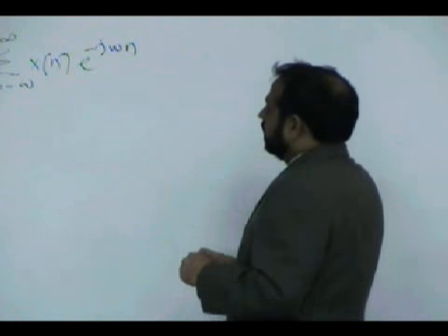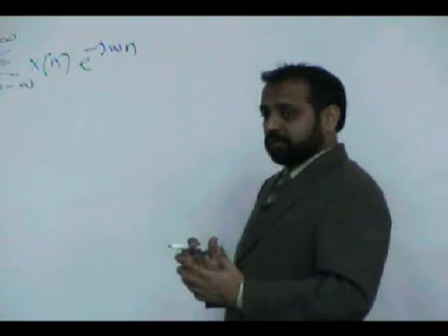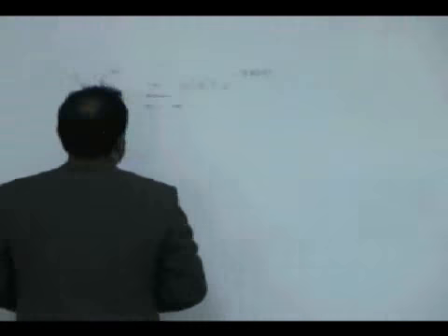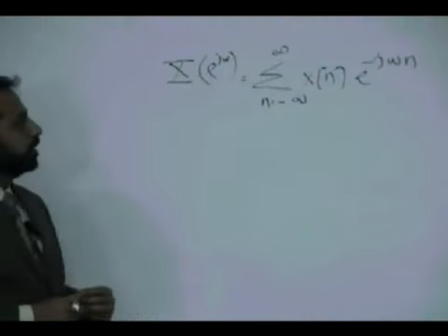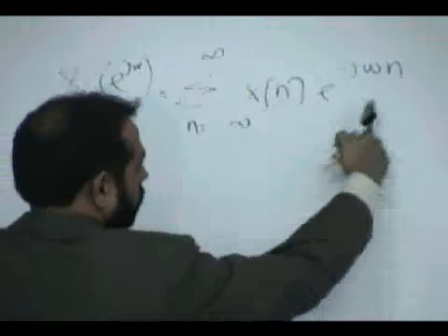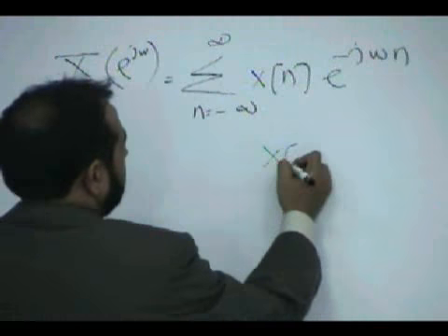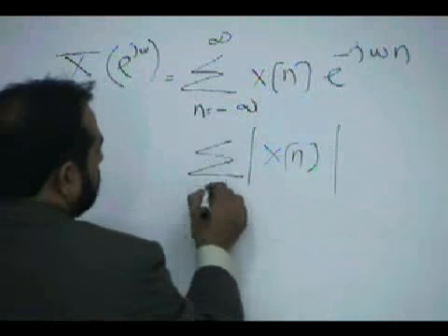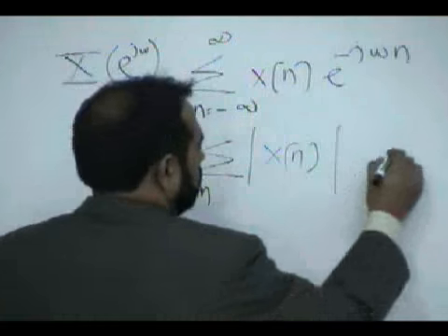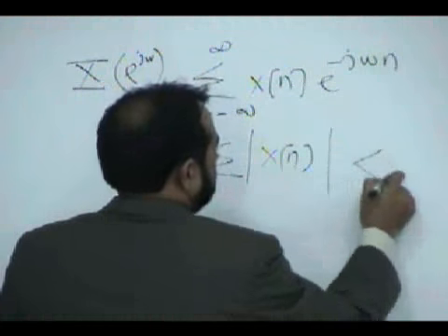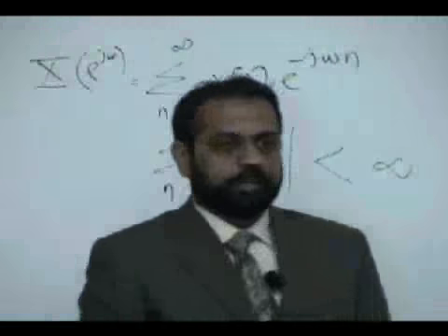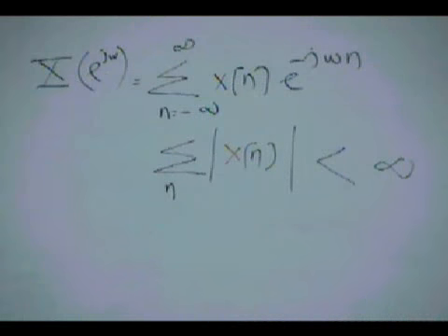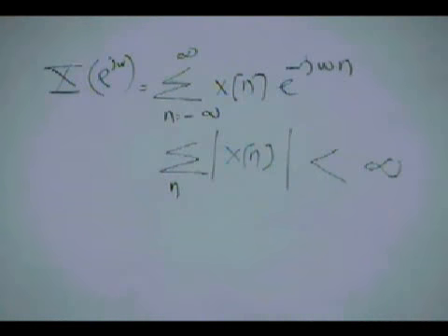So Z transform is another transform, and the reason for using another transform is that the Fourier transform, we know, is only valid if x[n] is absolutely summable, so the summation is less than infinity. If it is not, then you cannot use the discrete time Fourier transform. You cannot compute the discrete time Fourier transform as a closed form expression.